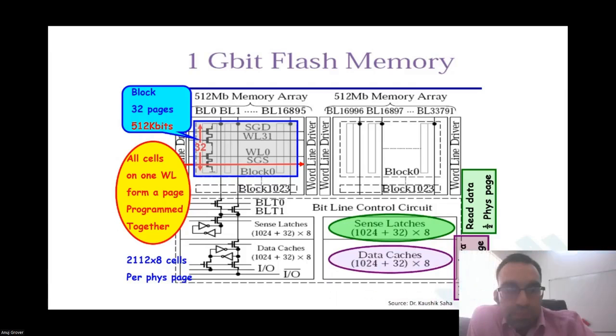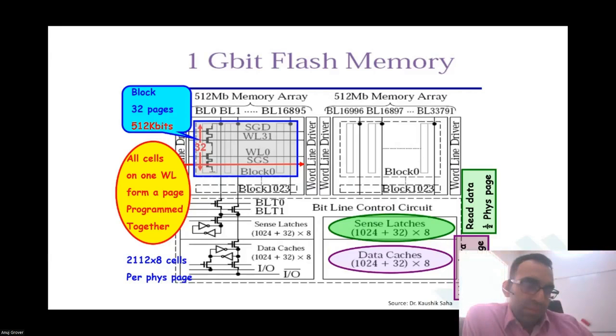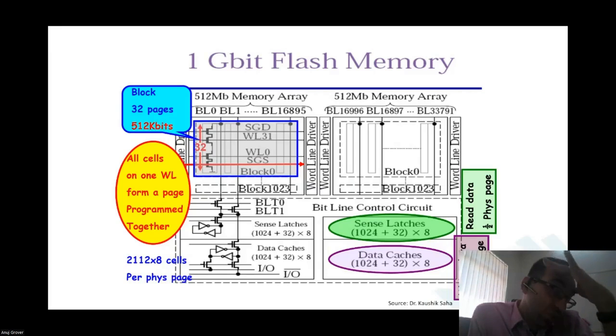Sir, would that also mean lesser number of bits will be required for error correction? Why would you say that? Sir, what does it depend on? The number of bits in error correction? Is that the size of the word? Yes, the length of the word. For example, if the word is 32-bit wide, you will need for a SEC-DED code 5 error correction bits. So it's like parity generation, something like that. Parity is always 1 bit. Okay. But error correction code generation is dependent on how many bits your data has.